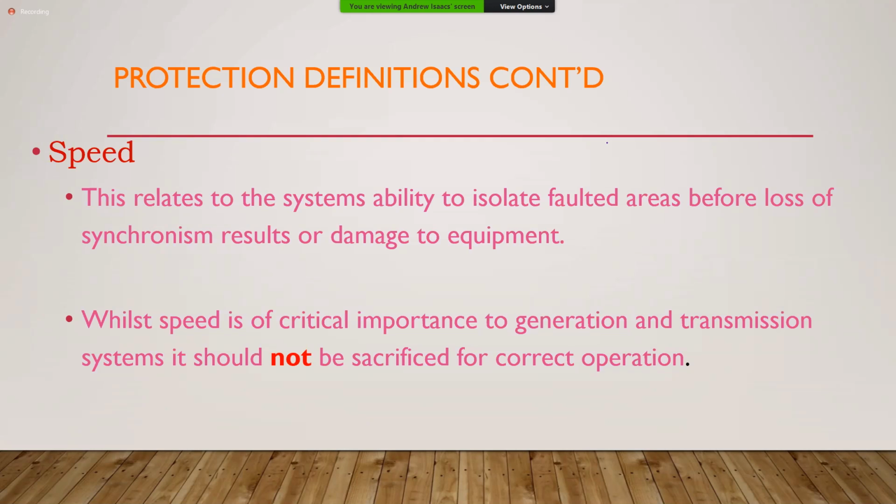Remember earlier we spoke about the fact that the flour mills has its own feeder, right? Now, if for whatever reason the flour mills is in full production, and they are pulling maximum power from JPS, and then suddenly it trips, that's a significant loss of load, right?